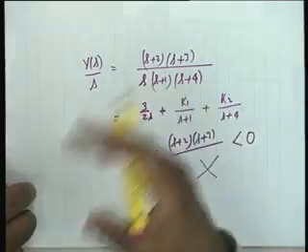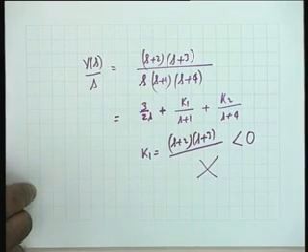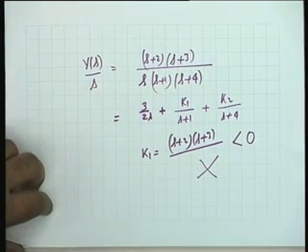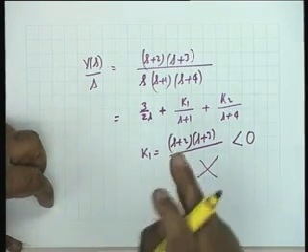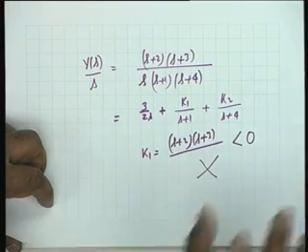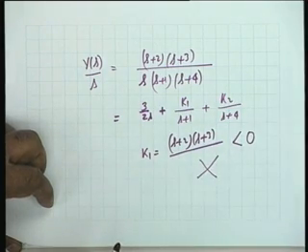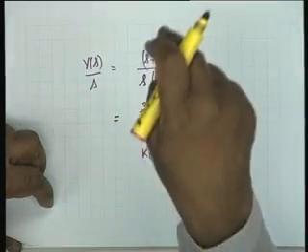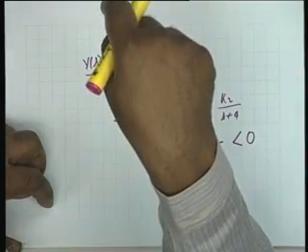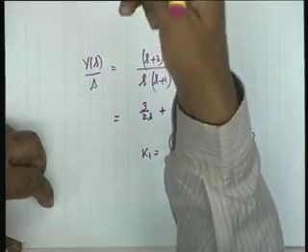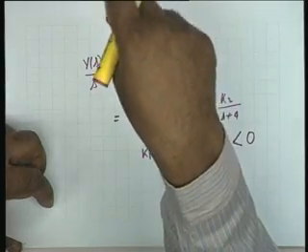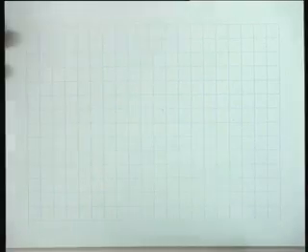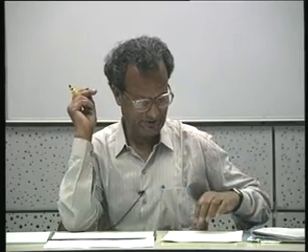Similarly, you can try the reciprocal of this, Z(s). In either case, if Z(s) works, then we know how to find it. But Z(s) also doesn't work. One of the residues comes out negative. Will Z(s) by s work? Because if it is RL, then you know Z(s) by s shall work. It doesn't work there either. I give up. I would not repeat this procedure.